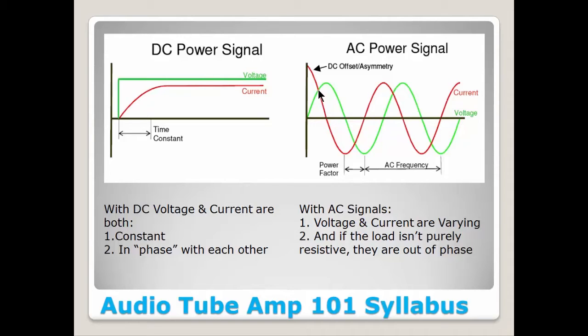You could put a meter right there and measure it, and that would be something you could then plug into your power formula and use. However, we're trying to measure power over time. Well, look at this point in time right here. The voltage may be positive, but the current may be negative at that point in time. You get into another point here where the current is flowing forward, but the voltage is actually negative.